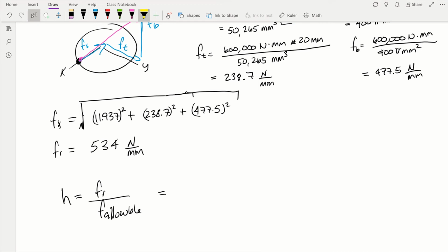So we can go to the table and look at what is the allowable force per inch of leg for an E60 material. And we're going to go ahead and use the values for the bridge type structures, which means that this guy can handle 8,800 pounds per inch, and this quantity is always per inch of leg length.